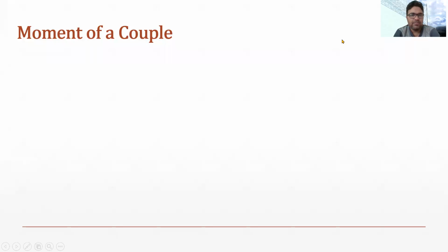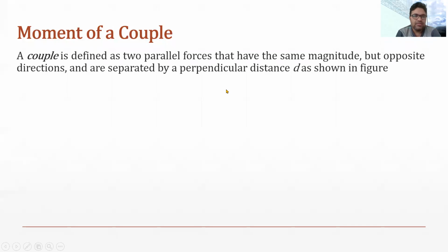Hello, welcome back. So in this part, we are going to discuss a very important concept which is related to the moment, and that is moment of a couple. The concept I introduced at the start of this lecture was actually related to the couple. Basically, a couple can be defined as two unlike parallel forces that have the same magnitude but opposite direction, and they are separated by a perpendicular distance d as shown in the figure.